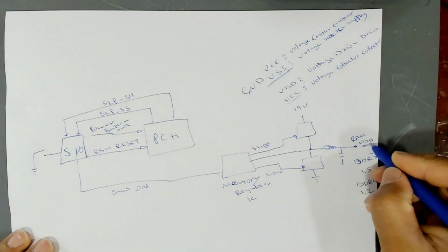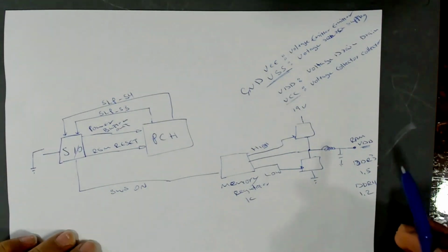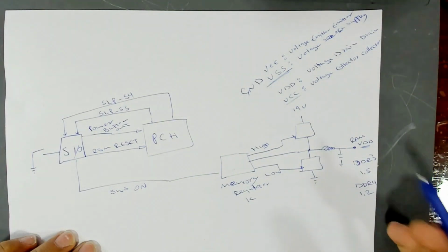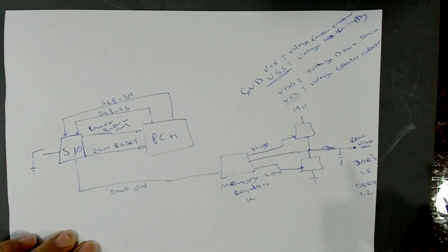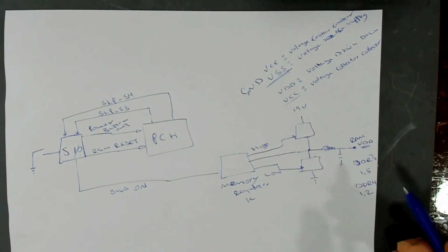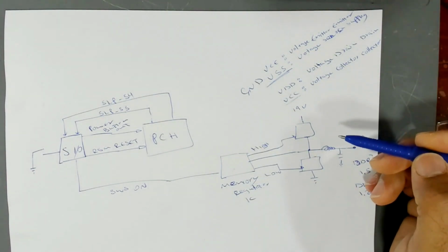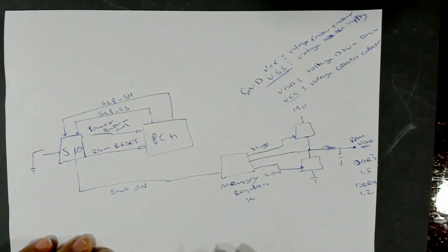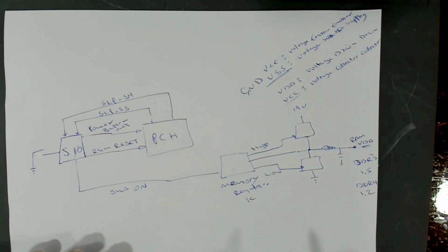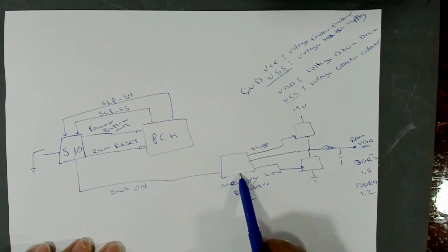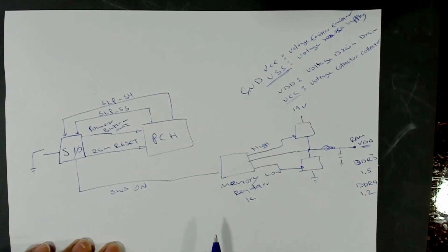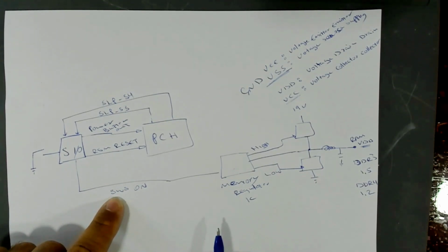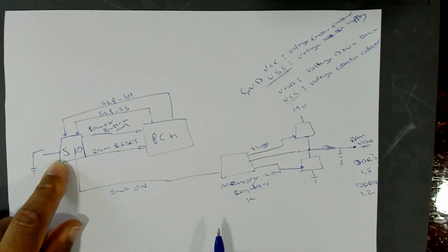So the RAM VDD, we said it depends on what type of memory is used. Is it DDR1, DDR2, DDR3, DDR4, and so on. So if you don't have this VDD voltage, it might be the regulator itself or the MOSFETs, or this enable signal is not getting produced by the Super I/O.